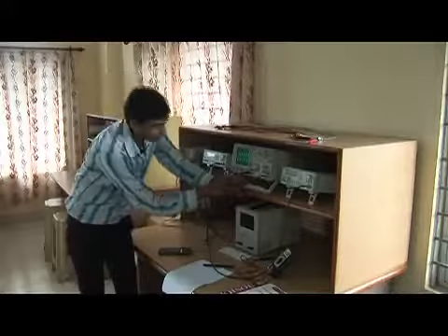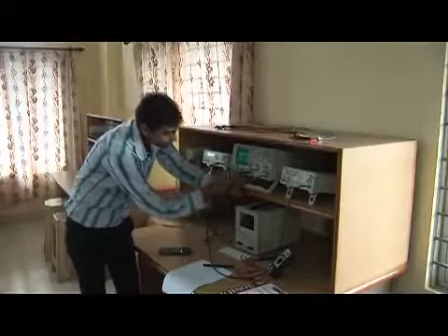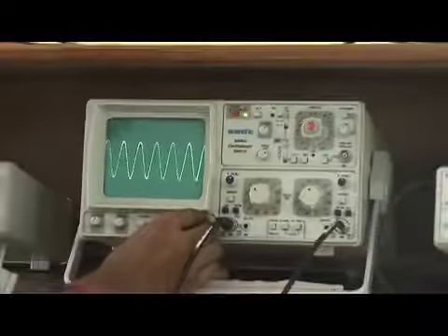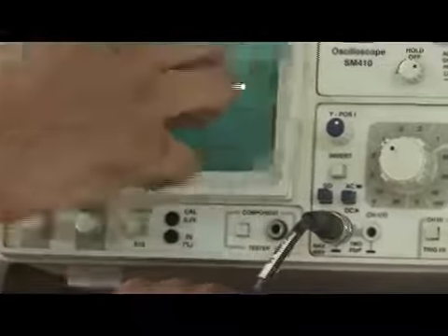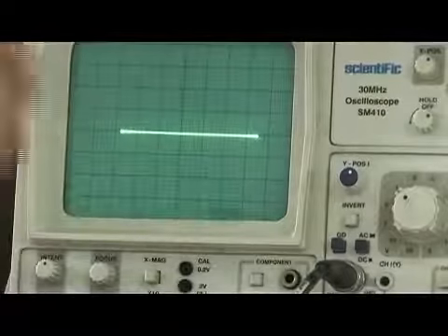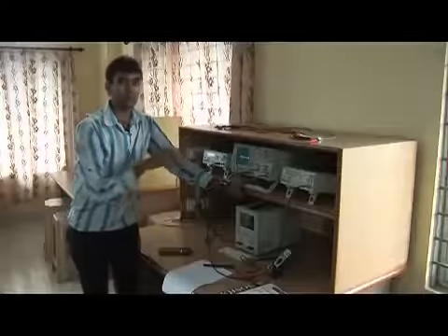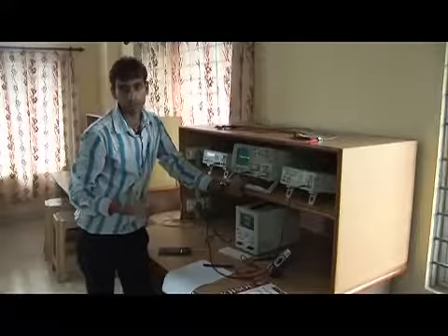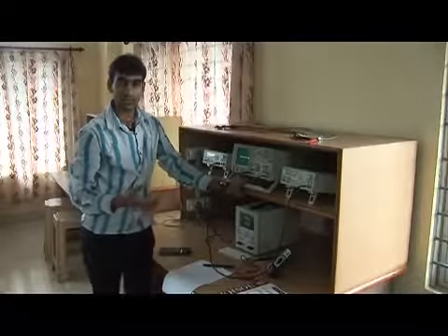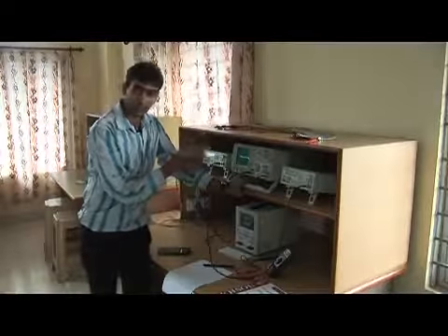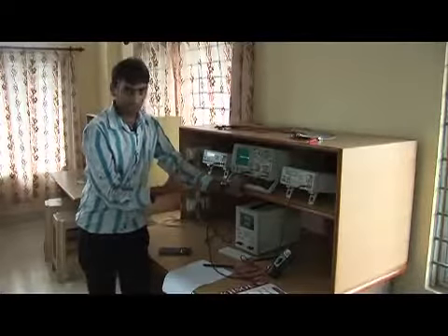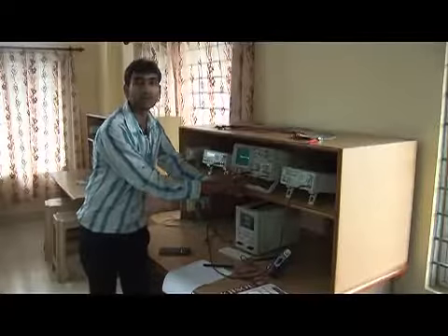It's not very important for this level, because when we insert a component over here, we'll get one figure, one view. That view will say whether your component is working or not. So that's why it is a component tester, depending on the figure. Generally, we call those figures Lissajous figures. You might have heard the name Lissajous figure. So what is the pattern of the figure? By determining that pattern, we say whether the component is working or not.